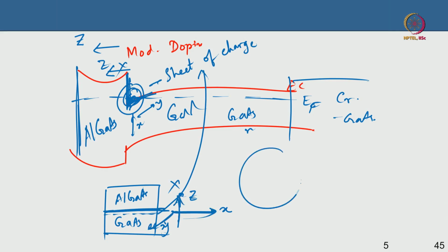So if I take a wafer, this is from the side looking at the cross section, if I look from the top, this is a gallium arsenide wafer, you are growing aluminum gallium arsenide on top of gallium arsenide, then the 2D electron gas is everywhere here below, but it can only move in this x and y direction. If I put a top contact here and a bottom contact on the back side, can you measure current? You will not measure current because vertically the electrons cannot move. The wafer will break down, but it will not move, okay.